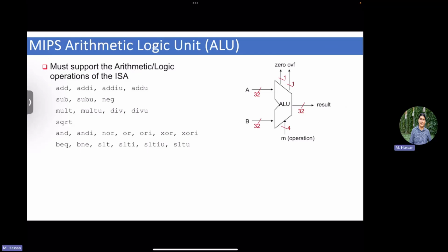Now, about designing those discrete components, the ALU, which is going to do most of the arithmetic operations. In digital design, I would assume you design the full adder, maybe a 32-bit adder or an 8-bit adder. Is that true? At the very least, you must have a full adder, and you cascade it to design a multi-bit adder, right? And then basically how the adder can work as a subtractor as well, right? A modern ALU is basically assumed to have all the arithmetic operations: an adder, multiplier, subtractor, and so on.